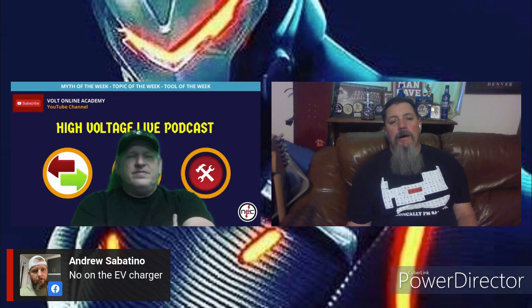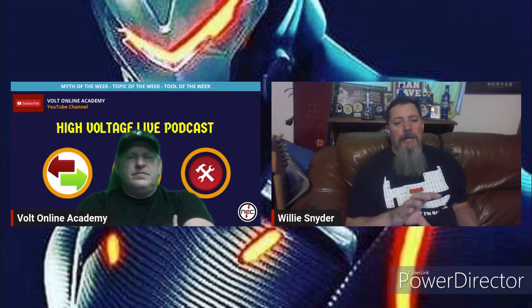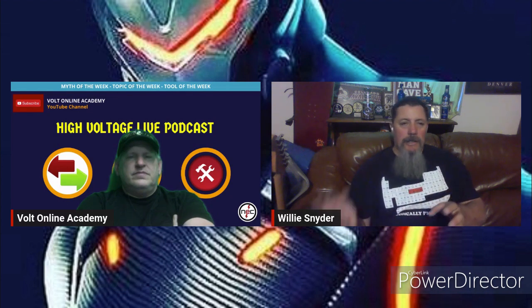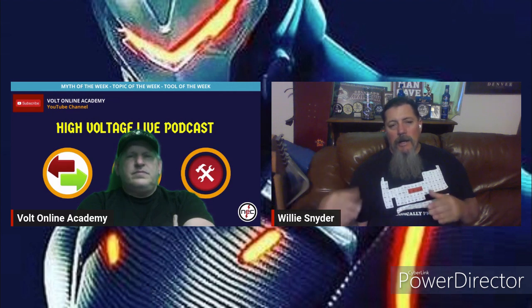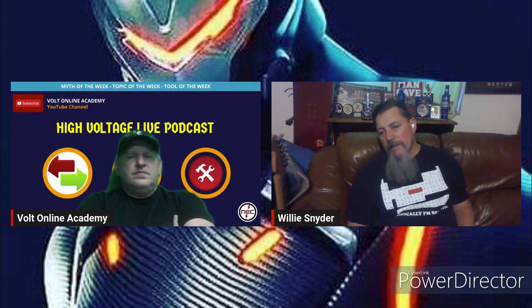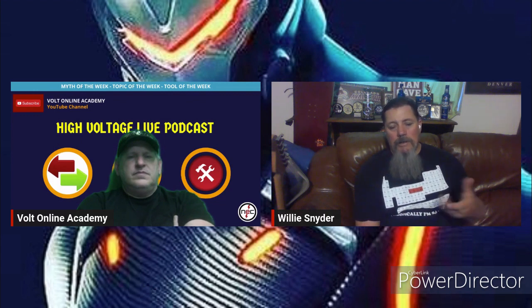So he's talking about on the EV charger. What we're saying is you have a breaker, 50 amp breaker. Let's say it's a 50 amp 2-pole, and then it goes to a bell box, and then you hardwire it to the EVSE charger, and then that goes to your vehicle. That's 100% code compliant. The breaker is sure, within 50 foot or line of sight of your equipment, so no disconnects needed. Now, if you go outside that 50 foot or line of sight, then you would need a disconnect. But if you hardwire the disconnect, then no GFCI is required either.